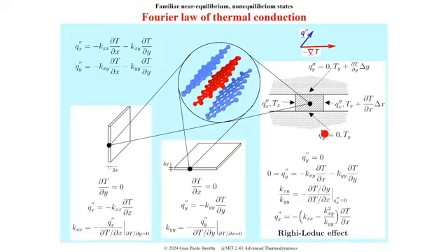And you subject your sample to a gradient in temperature in the x direction. Since this wall is insulated, the heat flux component in the y direction here is 0, and also here is 0. So you can assume that it is 0 also, not really precise, but 0 also in between, because this is supposed to be a small thickness of your sample.